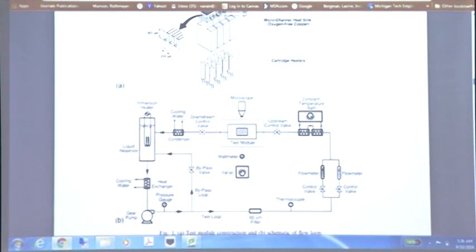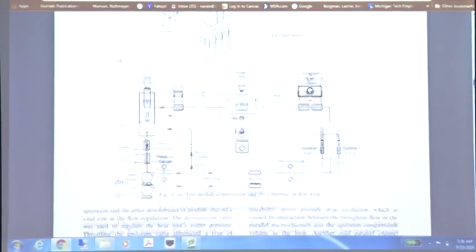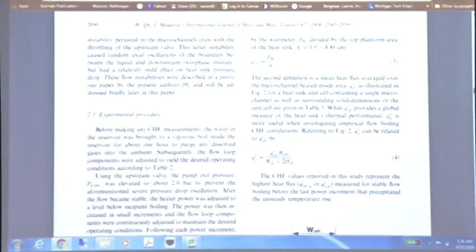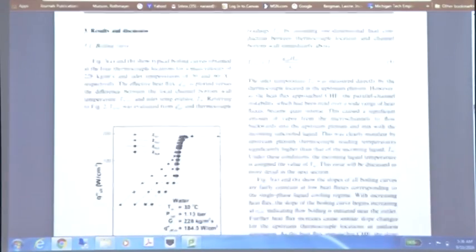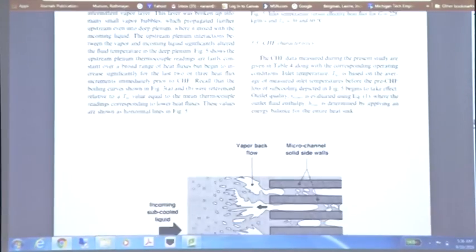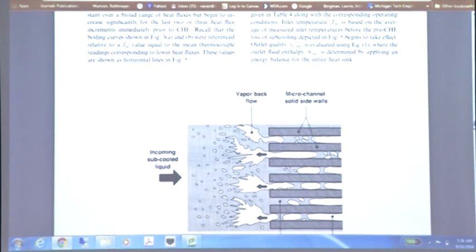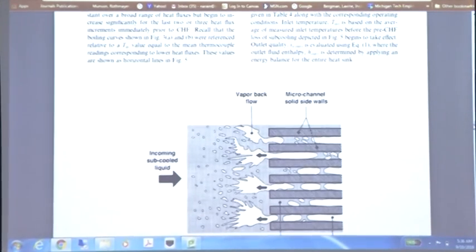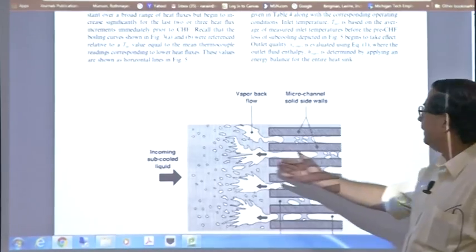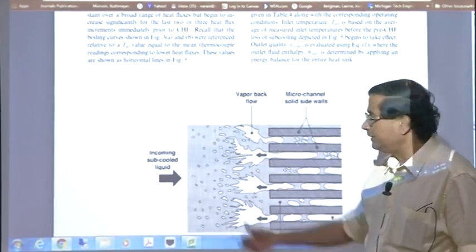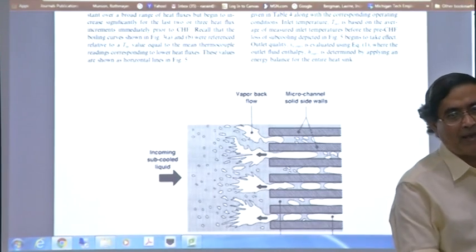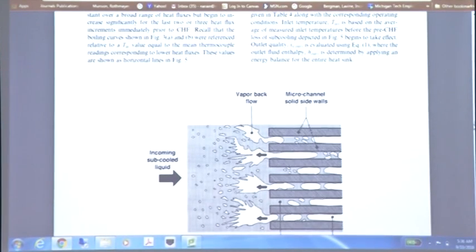And you need to have a flow loop and a module to look at. In this case, he's looking at it from the side, and one of the instability mechanisms that we mentioned, he sees that, let's see, where can I, yeah, right here. As certain heat fluxes increase and you try to feed liquid into a high heat flux thing, you see certain channels, it splashes back. It simply doesn't want the liquid to enter.